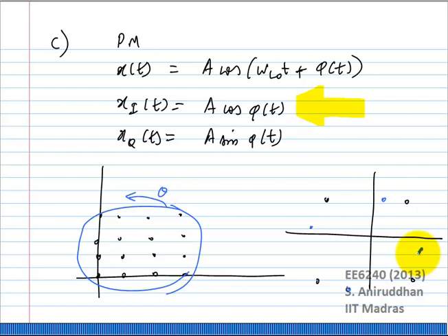Okay, correct. But what is the modern way of doing it? For the last, I would say 7 or 8 years, have you heard of OFDM? Orthogonal frequency division multiplexing. So what they do is, they split this 20 megahertz wide chunk up into a whole bunch of subcarriers. Each of these subcarriers might be carrying a QPSK or a QAM or something else, right?